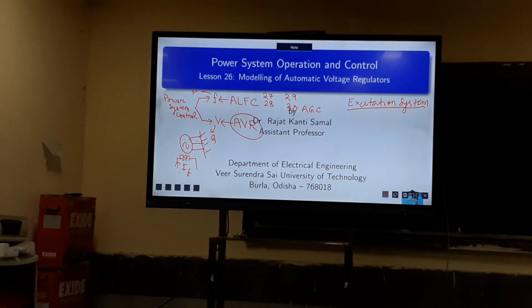In our case the conductors are stationary and you need the flux to cut the conductors. That flux cannot be time varying because you are rotating it. But in transformers, the conductors are stationary, so they don't generate a voltage unless the flux is time varying, sinusoidal, unless it is AC. So in transformers you have AC flux, whereas in electrical machines you have DC flux. Field excitation is always DC.